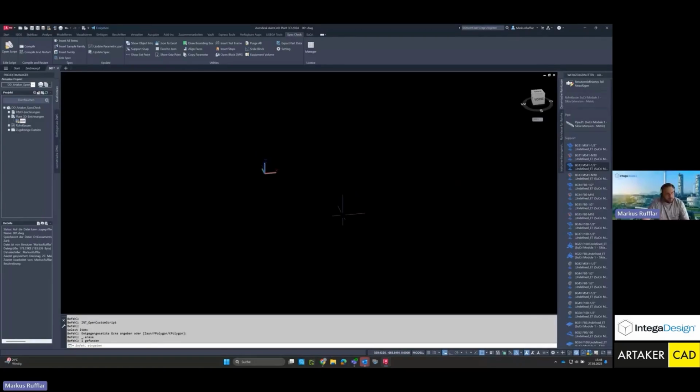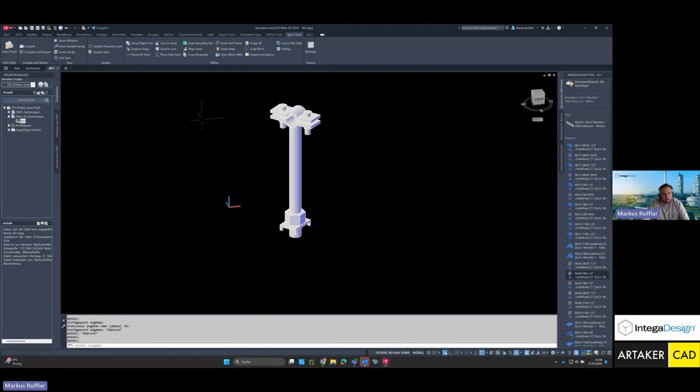There's nothing in it. And now when I've loaded the tool, I also see a SpecCheck ribbon here with the individual functions. So maybe let's start with the first function. Let's say I have a component here in my model space, and I'm currently developing the component, programming it, and I've inserted the component either via the pipe class or through other commands. Then I have my component here and I can see it, or maybe I'm inserting components from some other content pack, whatever it may be.